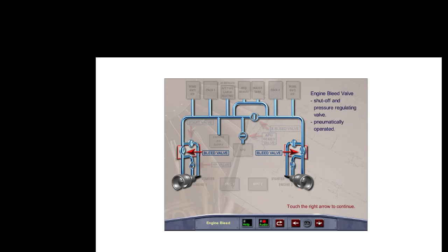Acting as a shutoff and pressure regulating valve, the engine bleed valves open pneumatically when engine bleed pressure above 8 psi is detected and the APU bleed valve is closed.